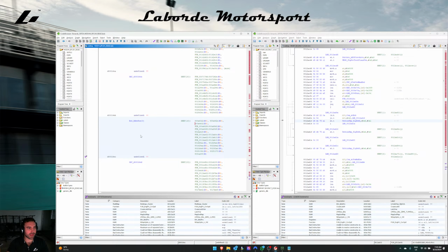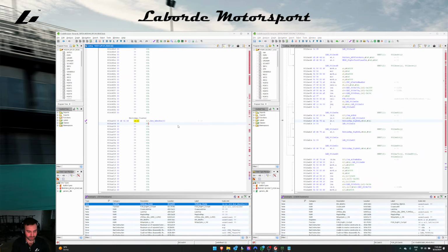And so what we can do now is go back to the cluster and use jump 0.t, which is jump if the bit at whatever position I specify is 0. So we're going to go bit position 0, and we're going to go to whatever address we're going to jump to. I'm just going to say 803C9FF0 as an example. It's going to jump up there, which may be our multi-map exit strategy. So if the brake isn't active, exit the multi-map functionality, because that's one of the preconditions for us to do the switching.